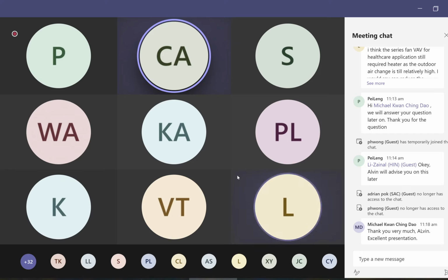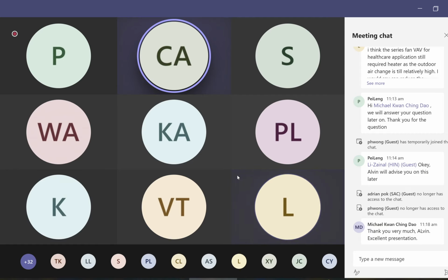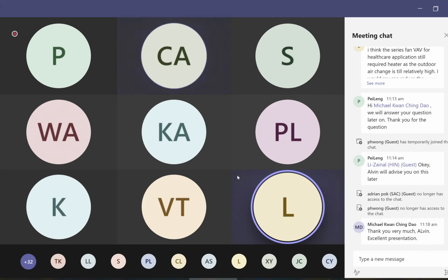That's why I mentioned, let's say the airflow that we require actually is less than the static pressure that we require. Yes, it's based on pressure build up, but we cannot ramp down so low in a certain area that you cannot achieve the static pressure. Yeah, correct. That is probably a control issue on that particular project. I don't think it's a control issue. It's a typical issue because there's always a lower limit for this VAV system. You cannot go down too low, the static of the AHU. Yes, of course. And any equipment design has a range.